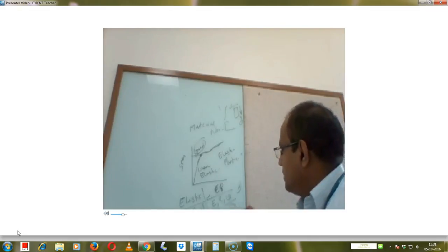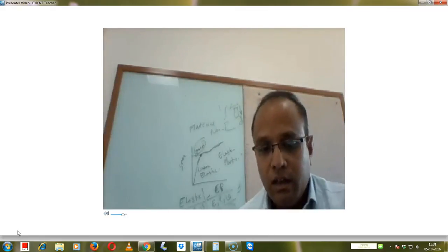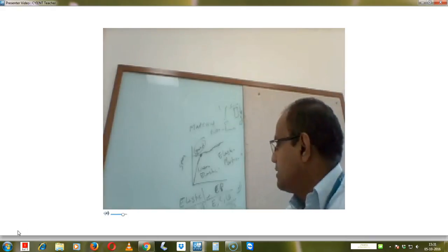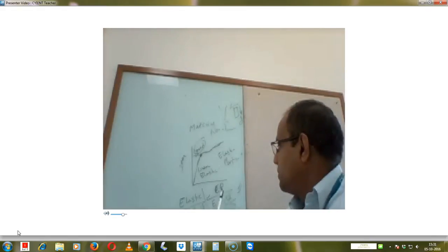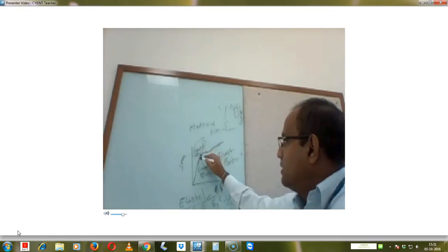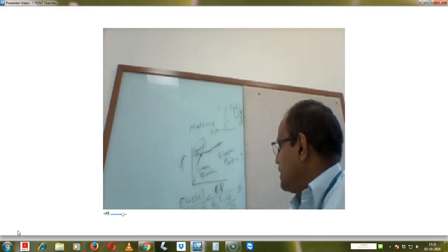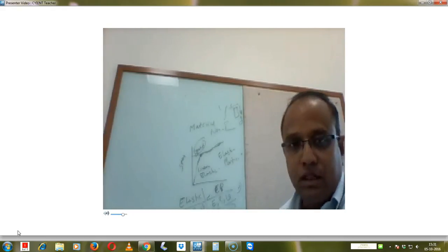Okay, bilinear and multilinear. These things we discussed in our nonlinear analysis chapter, so you can refer to those. In elastic, we need to give only Young's modulus, density and Poisson's ratio. In elastoplastic, we need to give elastic, density, Poisson's ratio, as well as the plastic curve. This plastic curve can be given in two ways, either bilinear or multilinear. So this is on material